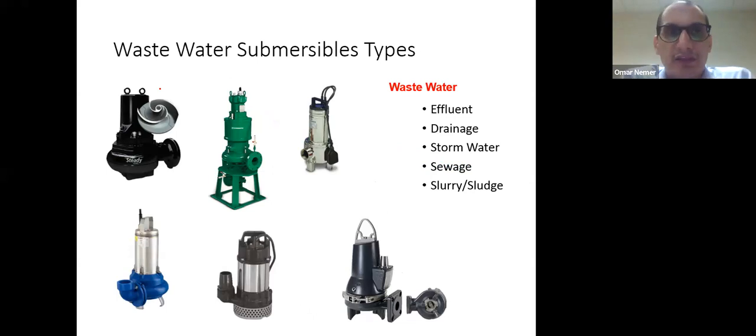But there is something we need to take a look at. There is one criterion we have to consider when selecting a submersible pump, which is the type of wastewater, because wastewater is a very general term, and this waste can be differentiated.